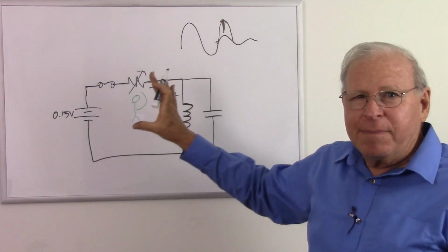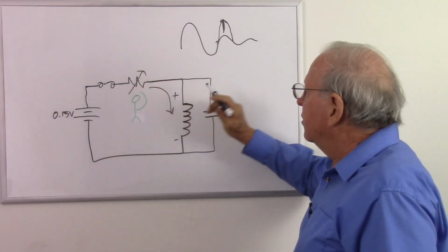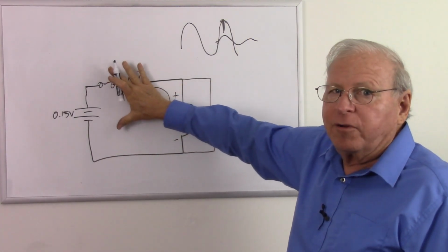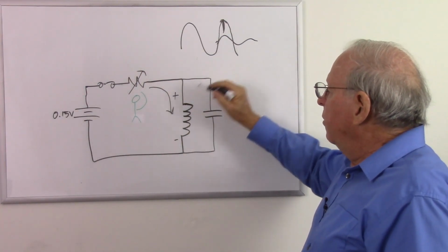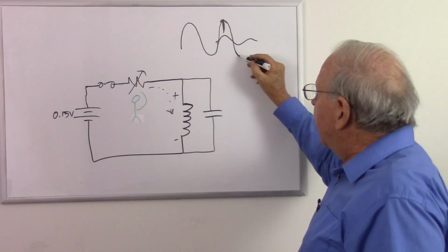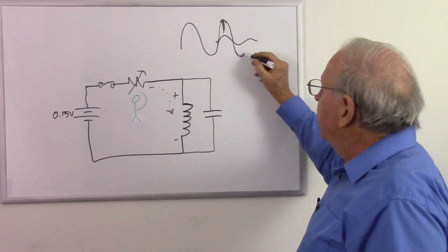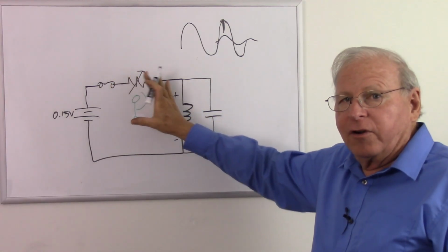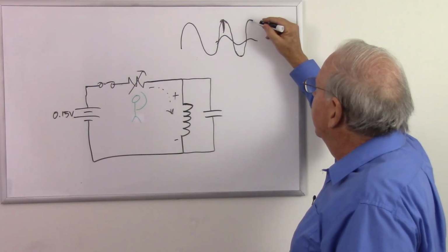But he doesn't want to keep it there because he's pushing the voltage up. We want to allow the voltage to come down now. So he's going to push this up to a very high impedance so we don't have much current flowing in, so that we allow this to go down in voltage. But then when it starts to come up again, he's going to start decreasing his resistance, allowing current to go in and push that back up.